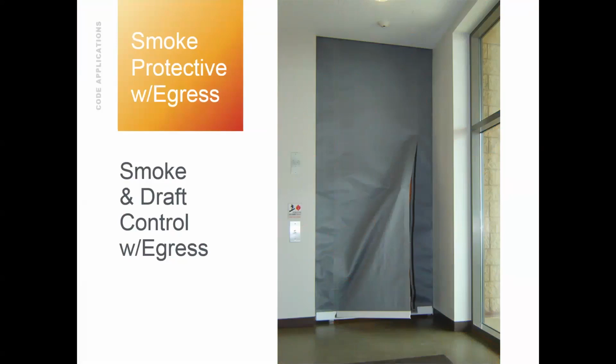This is greater than 15 feet in height. So with 1 barrel, we can go a maximum of 30 feet in width, but unlimited height. So this is well over 15 feet in height. We're still going to use this 1 barrel for this application. Still within an intended path of egress.